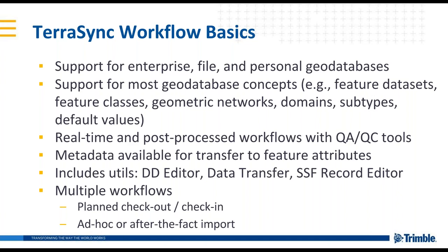And the last thing on the list was default values. We support any of the default values, or fields that are required or not required. Those are all supported and come out to the field into TerraSync based on whatever you have defined in your geodatabase. We support both real-time and post-process workflows. So although the post-processing is done in ArcMap from within the Positions desktop environment, you also have the full ability to use all the capabilities of TerraSync with setting up TerraSync for real-time sources, etc. And any data that comes back in will be seen as being real-time and corrected in the field.